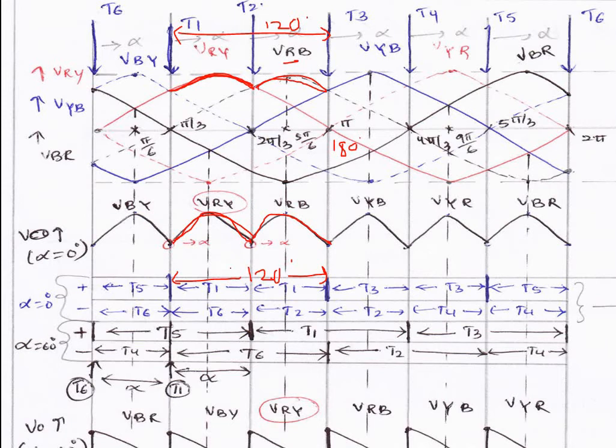So the full conduction period is over for T1, and after that in the positive group T3 will conduct. Similarly T2 in the lower group should also conduct for 120 degrees, in the sequence T1, T2, T3: 60 degrees with T1 and 60 degrees with T3.